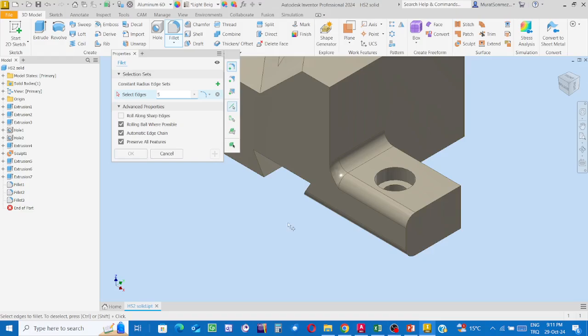To be able to prevent excessive stress within the body along a sharp interior edge, this is the recommendation: round the edge. Stress means atomic bonding forces per unit of area. In engineering we use stress, not force, but force per unit of area. Stress means atomic bonding force divided by the area of the surface in consideration.